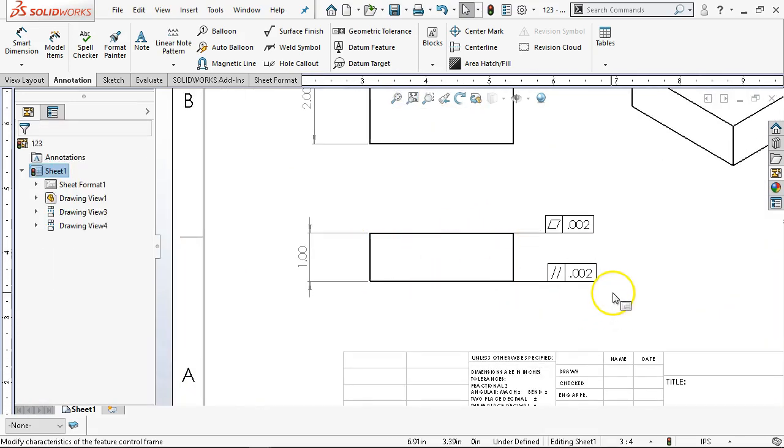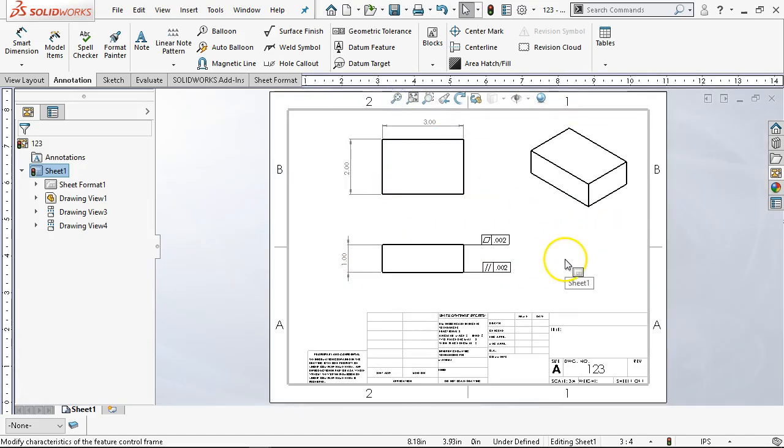All right. So when we look at these tolerances, the flatness at this lower level, if it grows to this, it's still within the capability of the tolerance to hold the plus or minus 5. Maybe that's a better way to say it. All right, we're going to have to do stack-ups. So right now we're just going to place a couple of tolerances, get a feel for how this works, and then I want to look at the conditions that would be able to generate those items.